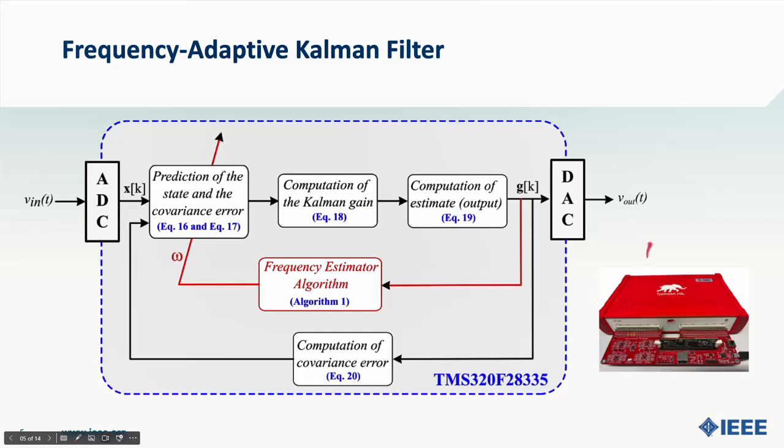This picture already shows you the controller hardware-in-the-loop result setup, in which I'm going to run the proposed algorithm in the microcontroller, and the Typhoon HIL here serves as a kind of signal generator to input the signal, vary the frequency, and apply all the perturbations that I need.